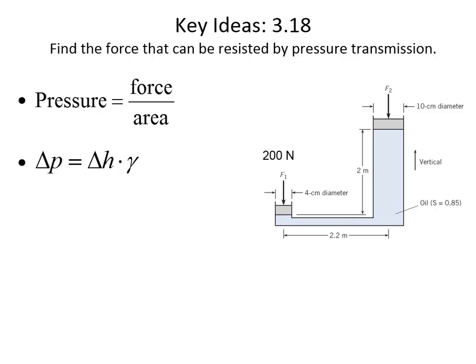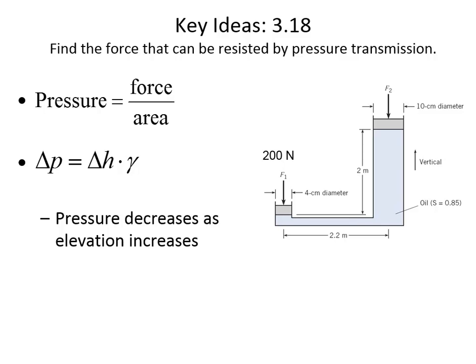So on this one, the pressure isn't going to be the same. The pressure here at that surface is not going to be the same as the pressure there at that surface. The pressure at 2 will be lower than the pressure at 1. If this is 1, this surface, the pressure at 2 will be lower because as you go up through a fluid, pressure decreases. Any questions about this one?